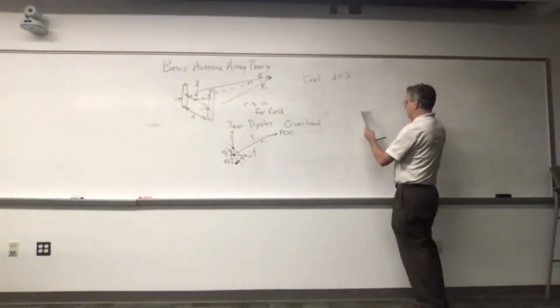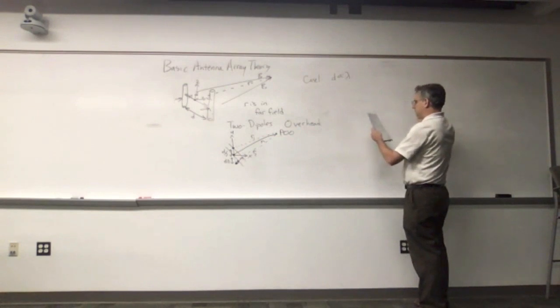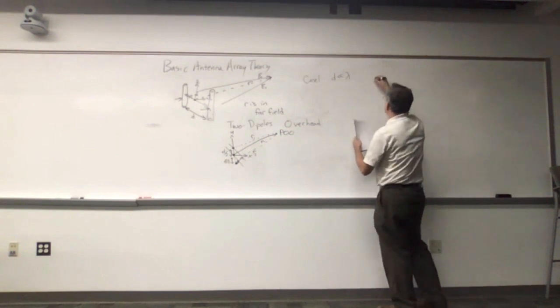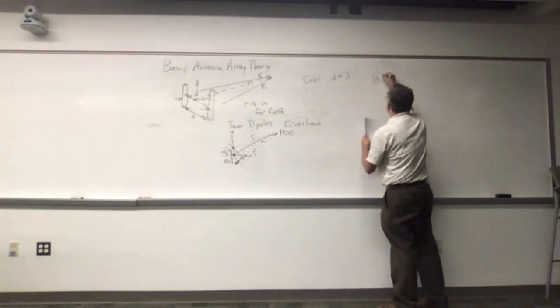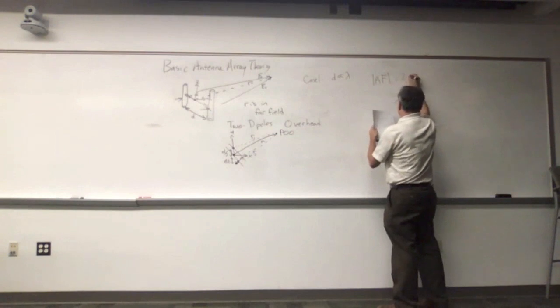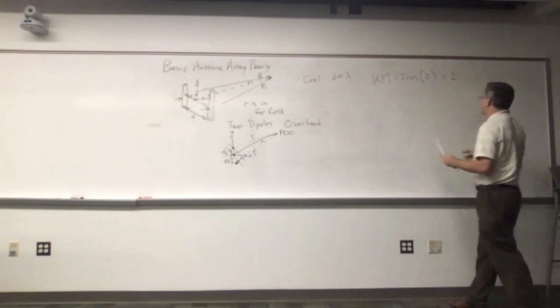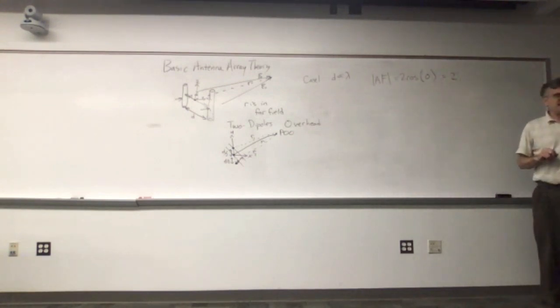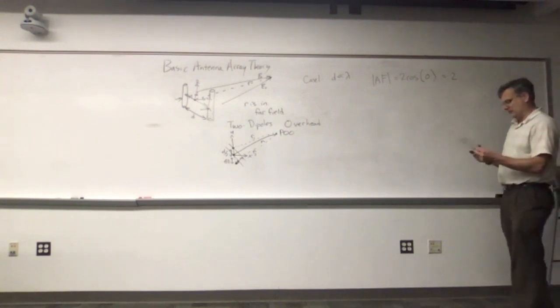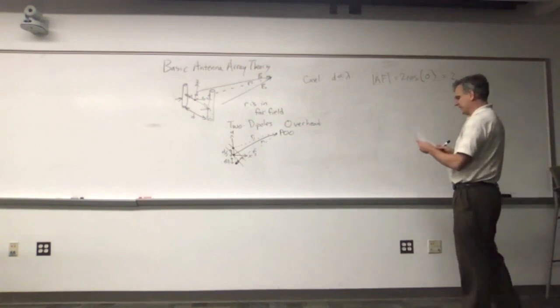And my array factor here is going to be equal to zero. Oh, good. No feed dependence. That makes sense. If I basically take two elements that are omnidirectional, I put them right next to each other, that's a nice sanity check. That should just mean continued, constructive interference in every direction. Okay. Now, the second case,